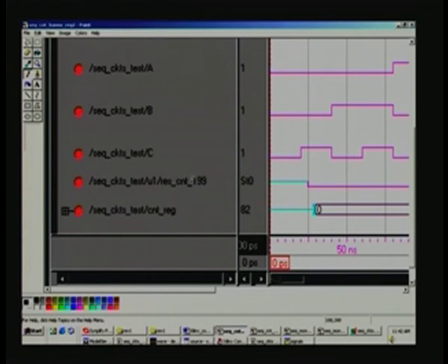And here reset count also got changed a little. It has been renamed as some 199. So, it takes a more detailed manifestation here as far as the signals are concerned. In the sense, if it is multi-bit where it was reported as one group earlier, in this back annotation it will separate out all the signals and report them separately, and it will be very tedious for you to keep track of the count, etc.